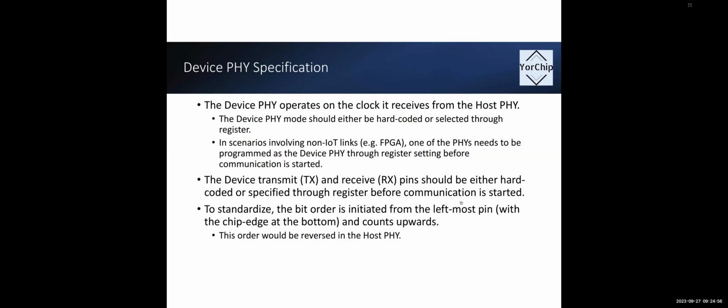Hypothetically, let's say you have a 12-bit ADC, and you want to do a factor of 2 serialization. You assign 6 bits to be transmit, and then 2 bits for receive for whatever control or dynamic adjustment you would need. That can be pretty much hard-coded, or if your ADC has flexibility, you change the register, or you change the EQs or something like that to adjust in that manner.